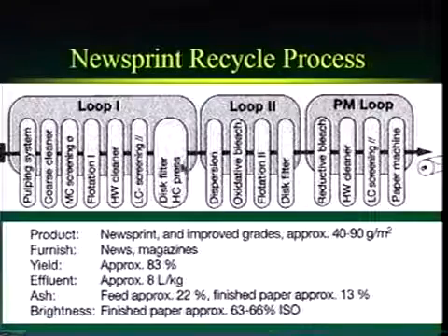That should get us up to about 30% or so consistency, and what that does is it keeps all the water in loop 1 to itself, so that loop 2 is mainly solids, or a higher percentage of solids. At that higher consistency we've got a little bit of washing done, but not too much. And then we can do dispersion.